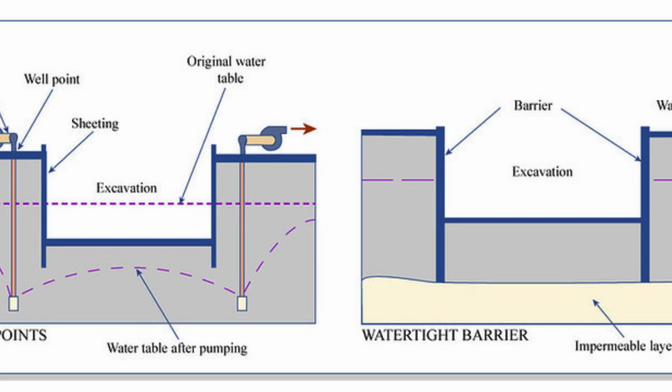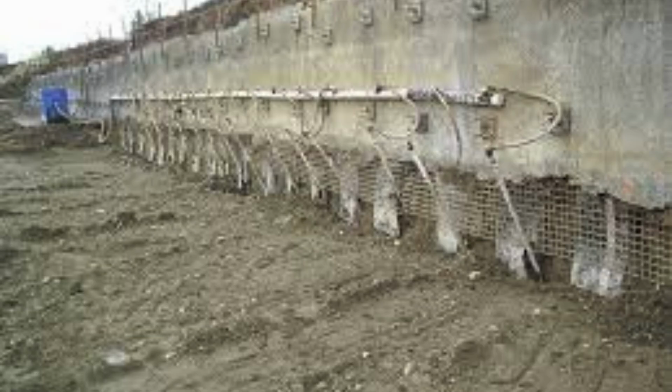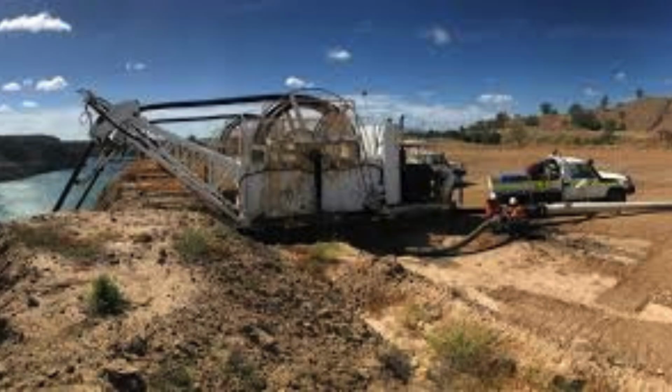Technique 2 of ground improvement is using drainage and dewatering. Ralph Peck, one of the legends of geotechnical engineering, once said, "Water in the ground is the cause of most geotechnical engineering problems. Drain the water out and the soil gets stronger and lighter." This is why you see those pump trucks on waterlogged construction sites. It's not just clearing puddles, it is improving the entire bearing capacity of the ground.